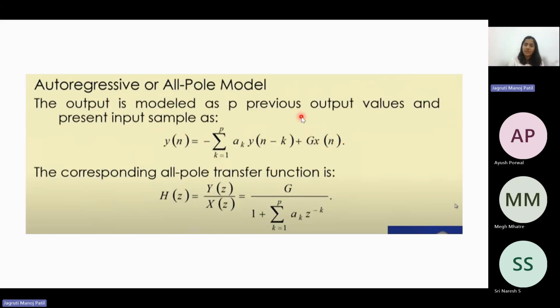Gain doesn't matter that much because normally you do not add a gain to your signal when acquiring data; inherently you have an amplifier for that. But people still keep that factor so that no problem occurs, and you can tune it if you want at some point. Then you have the past values of the output with respect to your autoregressive coefficients. You can again take the Fourier transform of it and you see a similar equation, but we do not have any zeros here, hence it is called an all pole model.